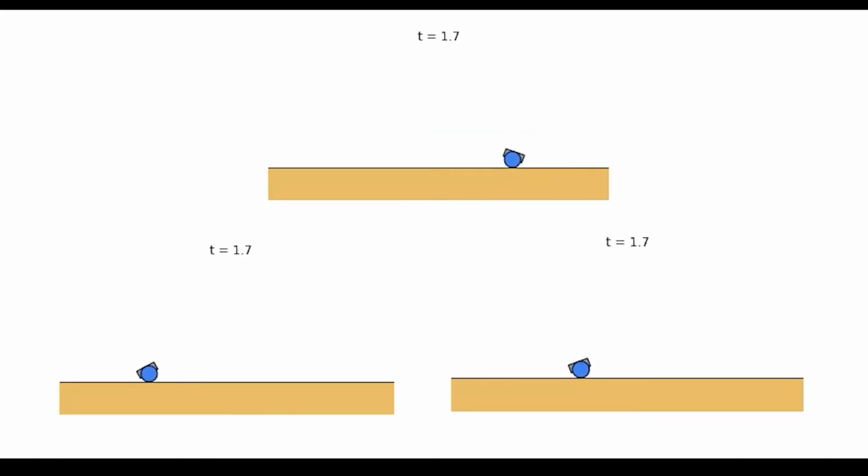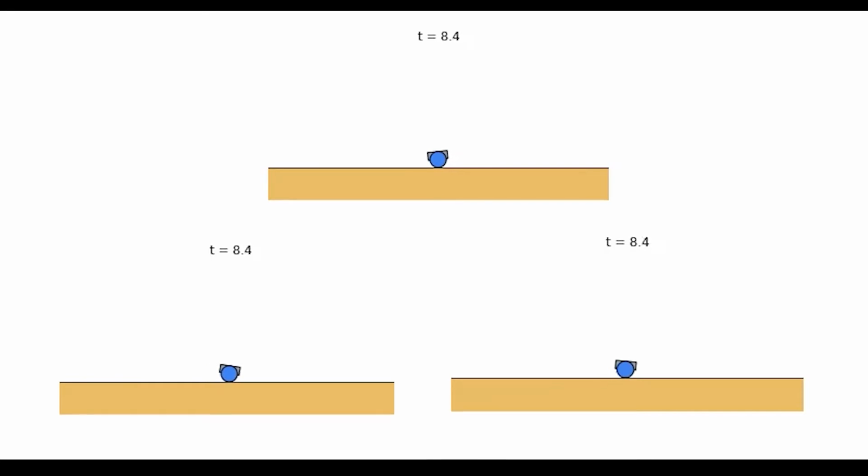For the LQR controller, we linearized the system around this top unstable point and created the controller around there. We found this controller easy to implement and surprisingly robust, even at extreme starting angles.